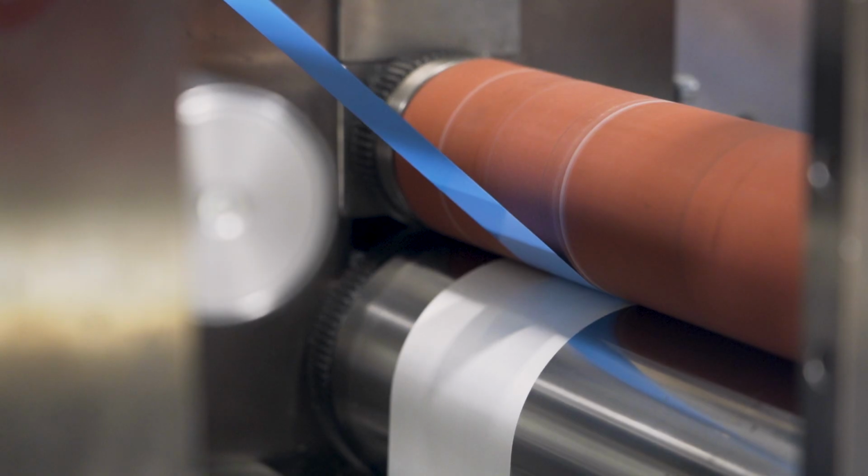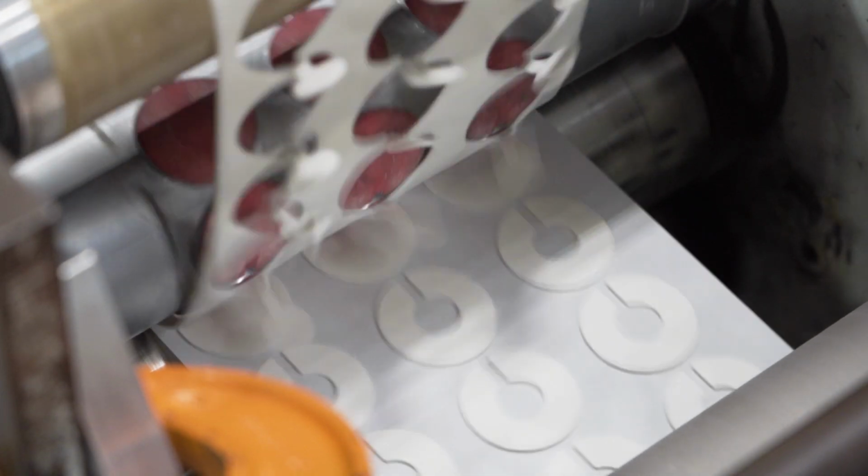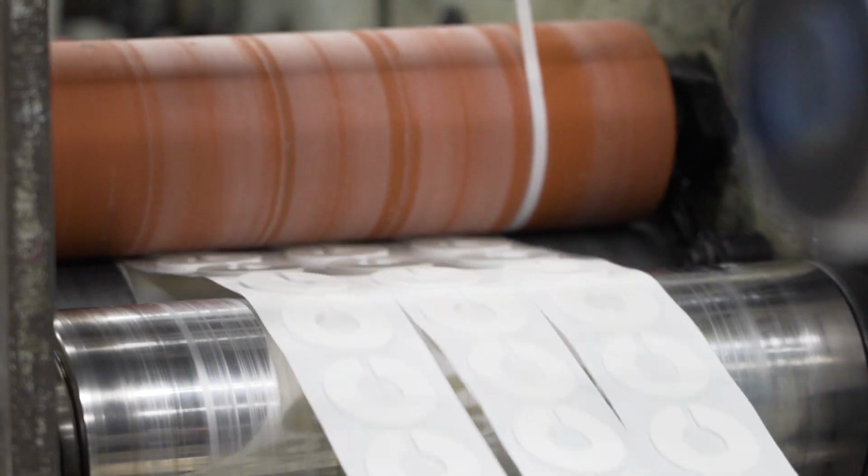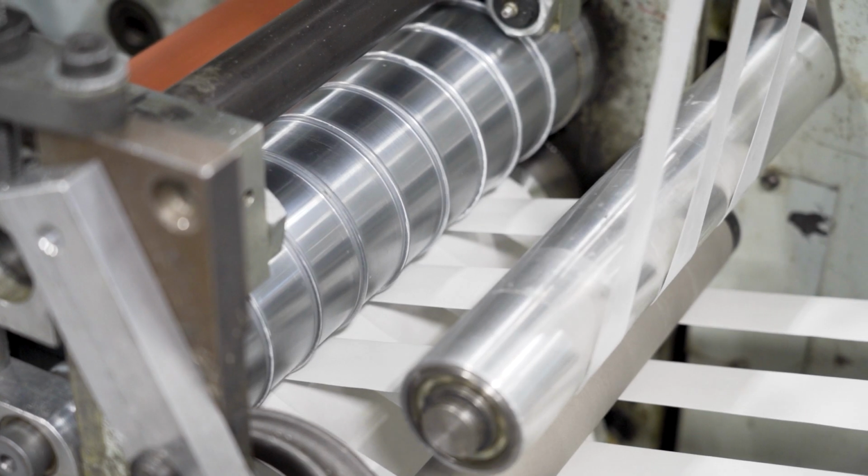Paper liners are cost-effective and easier to cut, but they are structurally weaker and more prone to tearing during die cutting. This can be especially problematic in high-speed converting or automated processes, where clean, consistent cuts are essential. Paper liners also generate more dust when cut, which can contaminate adhesive surfaces. This is a critical concern in industries like medical, electronics, or optics, where even small contaminants can compromise functionality.